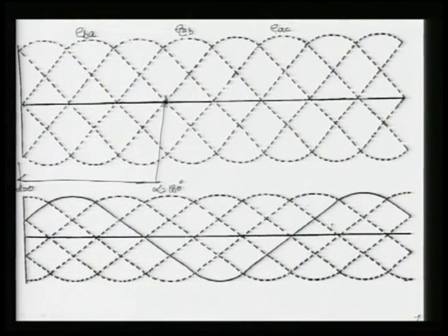So B becomes C and A becomes B, and here EAC, and similarly we can write the rest. Here it is nothing but ECA, a reversal of this voltage on top, and similarly this will be EAB. Before that, this voltage is the reversal of EBC.